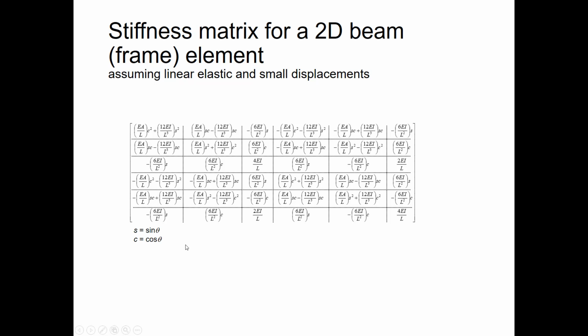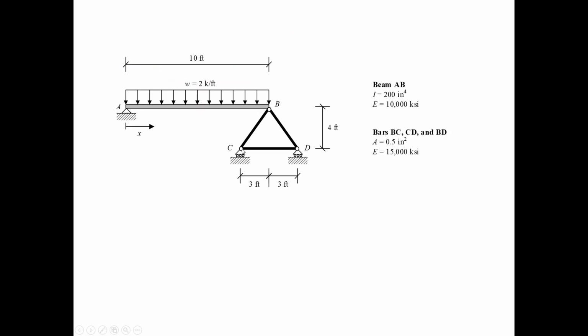is oriented in space. And so even though Abaqus has the capabilities of modeling beam elements and truss elements, what we're going to do is basically create our truss using these beam elements or these frame elements. And by introducing pinned connections between the members, we're basically going to turn these frame elements into truss elements. In other words, they will experience no bending because they're pinned at both ends.